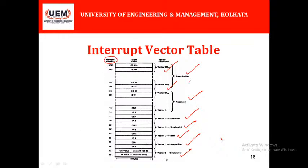For example, vector 0 is the divide error vector. Address 00 stores the IP value of vector 0, and 02 stores the code segment register value for the vector 0 type of interrupt. In this way, we can store all these interrupts.